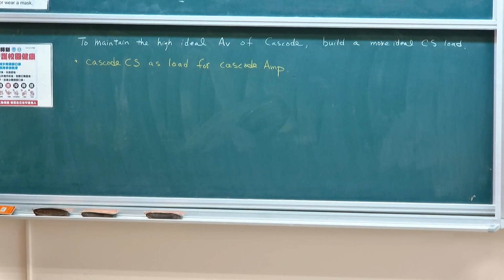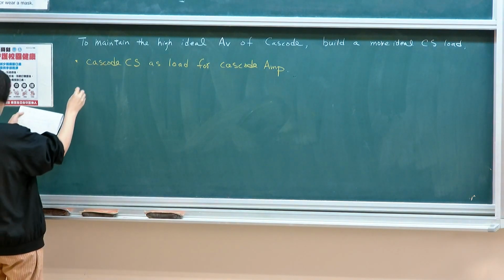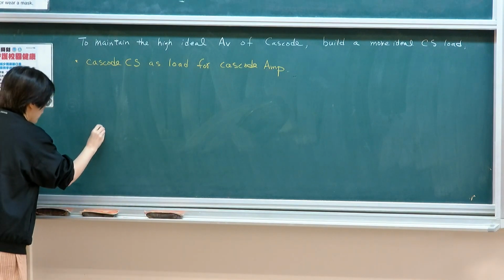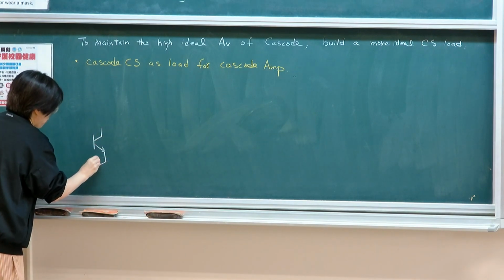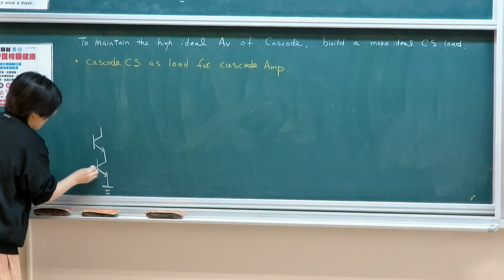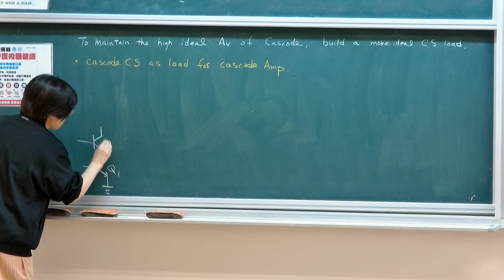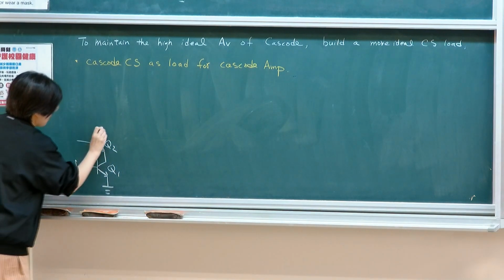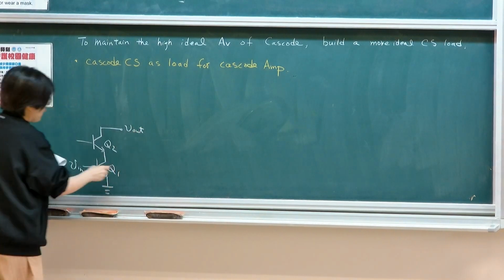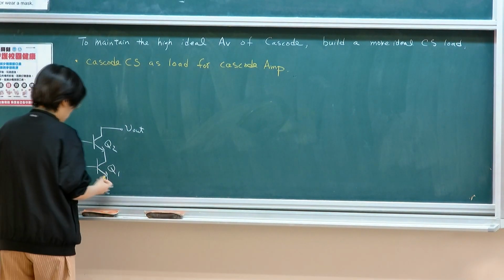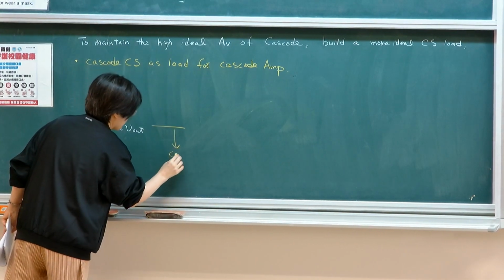That's actually the same difficulty. If you think about it, you need to isolate the node very well in order to provide the gain. So it's a painstaking process if you're doing this type of structure. You need to make sure that the nodes are very well taken care of, and there's no leakage path from this output terminal. So let's look at an example. As I said, I'm using a bipolar example. Q1, Q2, input, output. So this is the basic of my cascode amplifier. So underneath, this is the cascode amp.